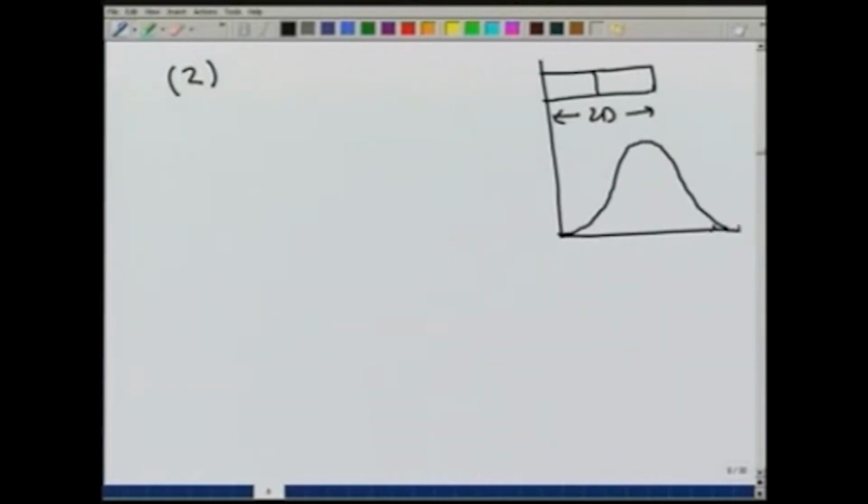So, we have a D hour unit hydrograph and we want to estimate the DRH for a rainfall of duration 2D and intensity, again let us assume that there is a constant intensity I. To make the calculations easier, we would assume that this I is 1 over D, but this I can be anything.